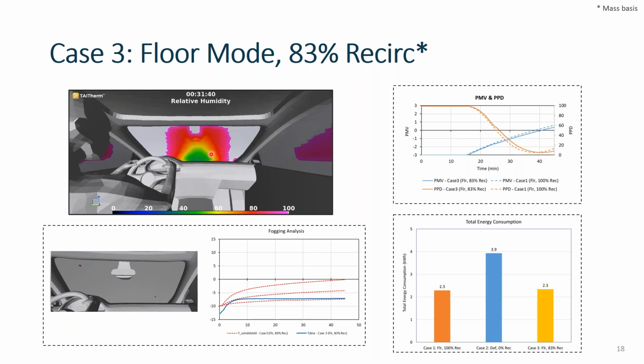So as the temperature of the glass warms up, you can see this fogging condensation decreasing a little bit over time. And to help proceed to the next case, this is probably pretty close to our optimal HVAC response. You can see we're doing a lot to mitigate some of this fogging for the warm up. However, it's not ideal. We still have some significant fogging here on the outsides, especially for the first 5 to 10 minutes.